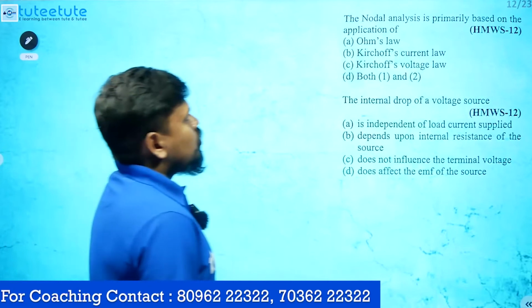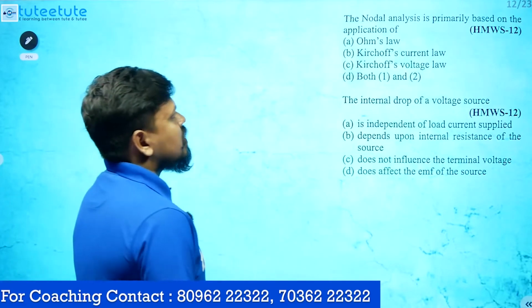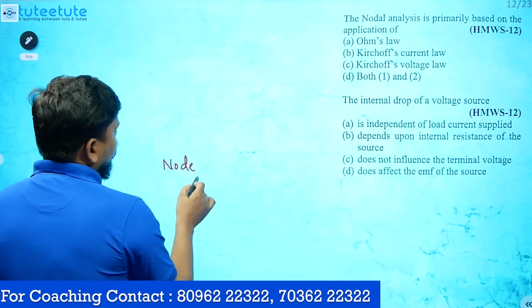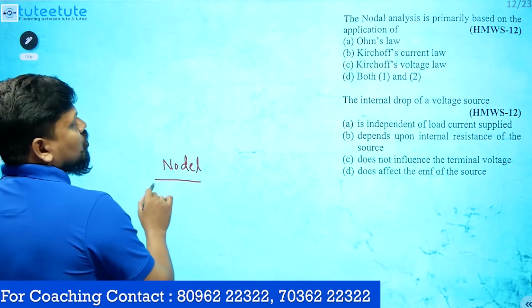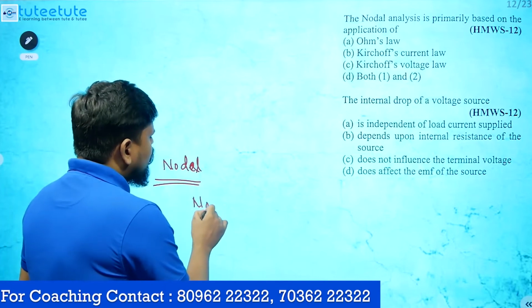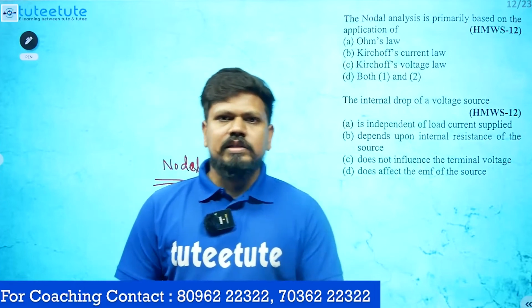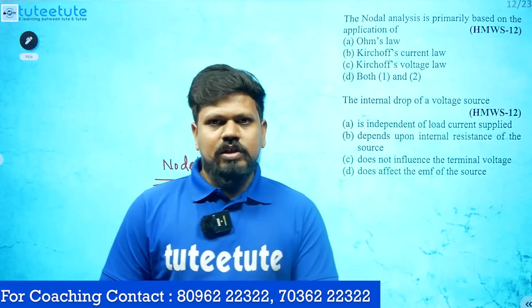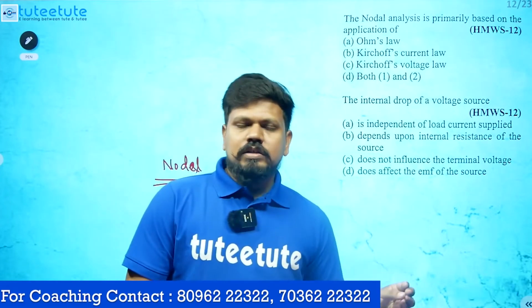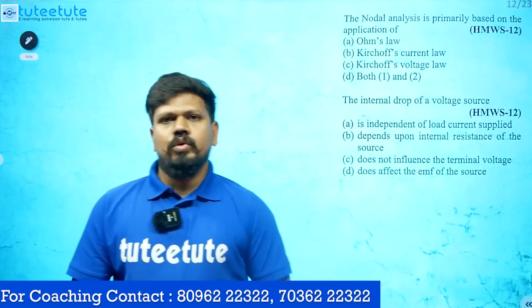Next question. The nodal analysis is primarily based on the application of what, they are asking. Nodal analysis means at a node we have to consider. At a node, what can you write down, KVL or KCL? At any node or junction, the algebraic sum of the currents is equal to 0. Otherwise, incoming current is equal to outgoing current.